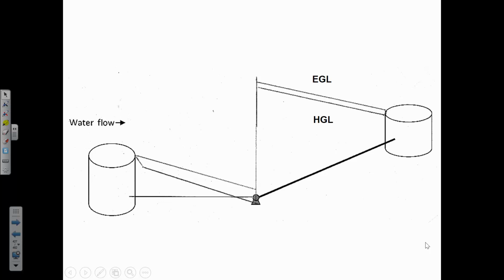Now how high does that have to be? Well, it has to be high enough that you can have a downhill to get you to the tank. You can't have it just be part of the way, because the water isn't going to be going up to the tank. It has to be going down to the tank. So you have to make this vertical line high enough that you can do the downhill and still reach the tank. But you want to make sure that it's not too high because we want this slope to be shallower since the pipe is larger.